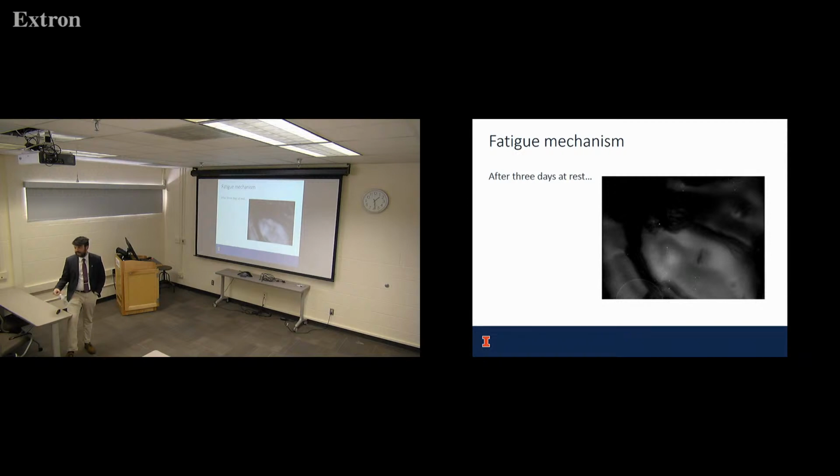But it's true, like I said, that's why we didn't publish the work, because we didn't do a heavy experimental matrix where we looked at what that healing looks like from a stress-strain perspective too. So we didn't measure the modulus again, for example. If you do some fatigue experiments and push it over the peak, you start to see some decrease in modulus. Then if you're truly healing, you should regain that modulus. So it's not necessarily even healing, because we didn't check the modulus before and after the test. That's why that part's a little bit fuzzy, and why we didn't publish it yet. We wanted to get the observable phenomenon first, then go back and characterize it. That's something we'll be looking at a lot more.